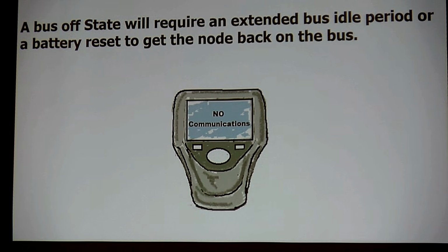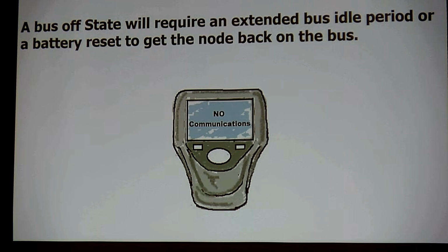I go to shops. They put a new module in because they couldn't talk to the module, and then they can't talk to the module when it comes back in a month. Well, guys, it wasn't the module the first time. He got kicked off of the bus. Before you start saying that the module's bad and you can't talk to him, you might want to do a hardware reset and see if he comes back to life. Because if he comes back to life, he was put in bus off state.